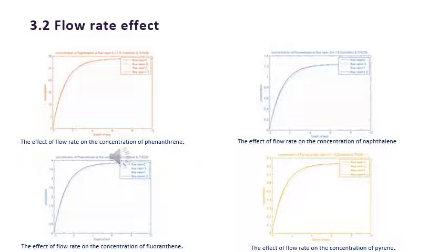As can be seen in the figure, the variation of polarity is not determinative of the concentration amount. Also, for various compounds, there is no significant change in concentration, from which it can be concluded that the main resistance against mass transfer is the internal resistance, not the external one. In other words, diffusion in the solid phase and reaching the surface feel the most resistance overall. The resistance of the liquid phase is low.